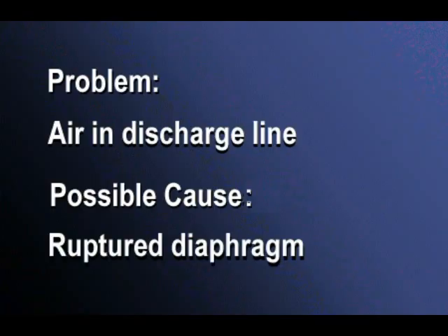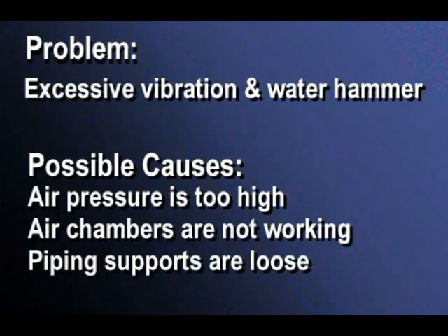Possible cause: ruptured diaphragm. Problem: excessive pipe vibration and water hammer. The possible causes include the air pressure is too high, the air chambers are not working, or a piping support is loose. To remedy these, reduce the air pressure, clean the check valves, or charge the air chambers.